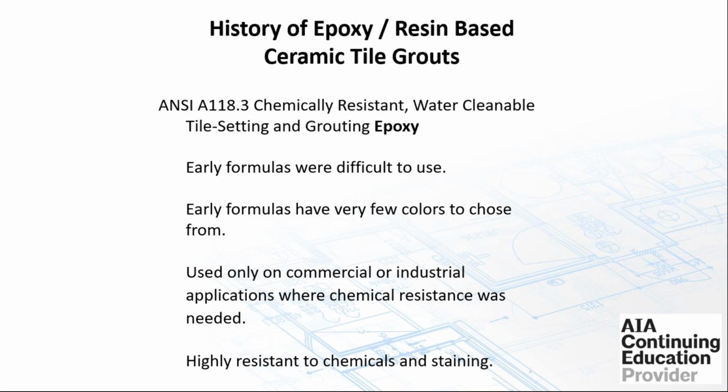When you look at the chemically resistant, water cleanable ANSI 118.3, both tile setting and grouting epoxy, early formulas, like I mentioned, were difficult to use. The early formulas had very few colors to choose from. Nowadays, the range of colors in epoxy grouts is the same as what you're finding in the Portland cement and the calcium aluminate cement grouts.